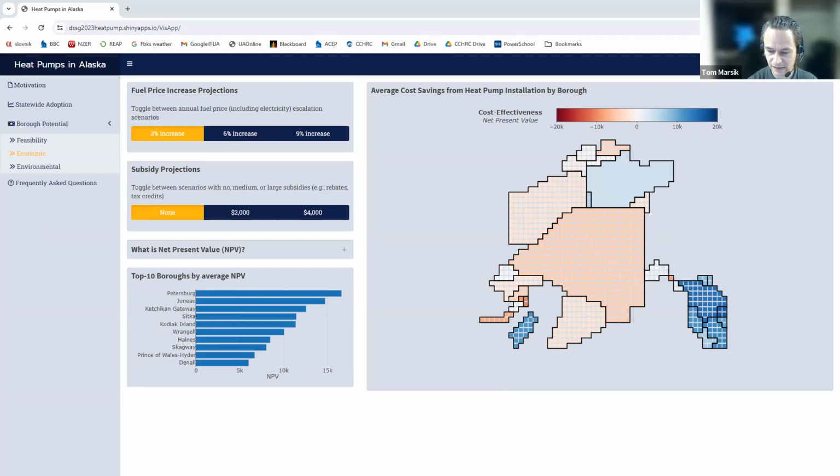It says Fairbanks gets hot in summer and most don't have air conditioning. I'll be interested in a two-way heat pump. I'm glad you posted this question because it's important to know that the ductless mini split system with just a press of a button switches from heating to cooling. So it has a reversing valve and it just reverses the operation. So that's one of the advantages of heat pumps, that you can easily use it for cooling also.